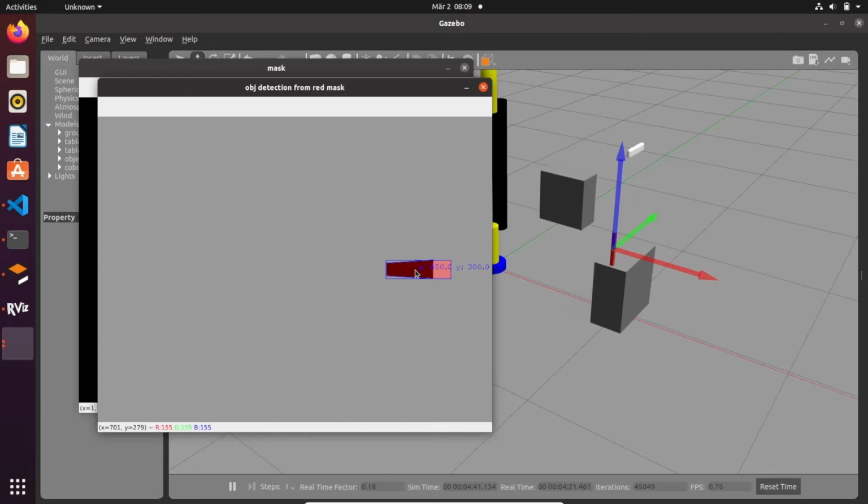So what can we do? Well, first we can exploit to our advantage the light of the environment, and we can see that on the top the light is lighter, let's say, with respect to the body. And this is something that we can exploit by adjusting the HSV maximum and minimum parameters of our code to create a mask that is only detecting the top. And from that moment on, we will be able to detect the center of this square that in 2D will be the center of the object itself in 2D. So we're gonna get the X and Y coordinates. So let's do it.